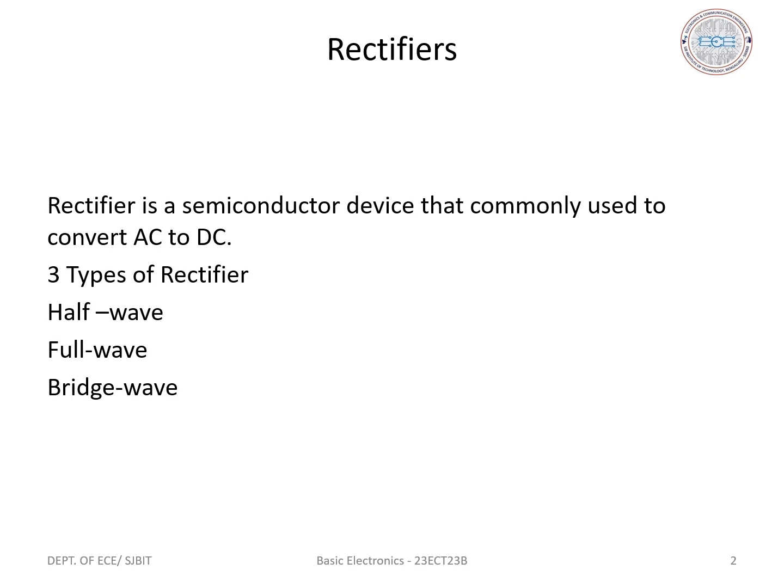So the half-wave rectifier consists of a single diode. It operates only on either the positive or negative half cycle of the supply, hence it is known as a half-wave rectifier. During the positive half cycle of the AC input, the diode is forward biased and hence current flows through the load resistance RL, meaning D1 will be in an on state. But during the negative half cycle of the AC input, the diode is reverse biased and hence no current flows through the load resistance RL. That is, D1 will be in an off state.